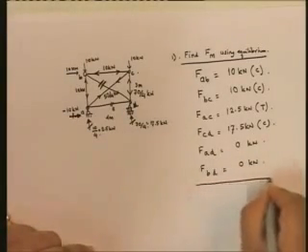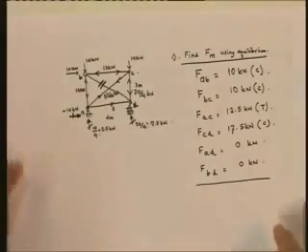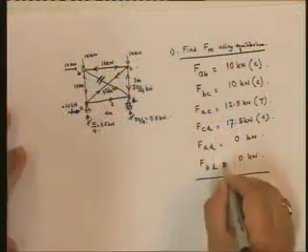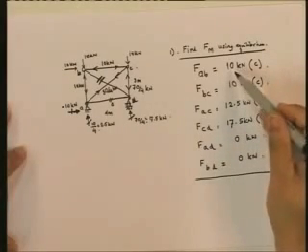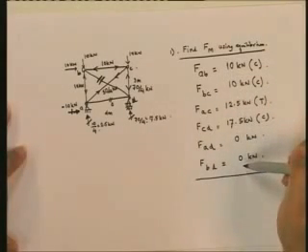Now what is the next step? The next step is actually to find out the deformations in all the members. That's very important. We need to find out the deformations in all the members. And what are the deformations in each member? Please look at it. These are all axial forces. So what are the deformations in each of the members?